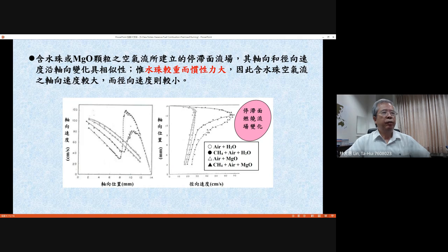For the flow, from the mass conservation, you will find out as the temperature increases in this region, the density will reduce, right? Then, based on the ideal gas law, when density is reduced, the velocity will be increased. Okay, this is the typical increasing behavior of your actual velocity to the maximum value.